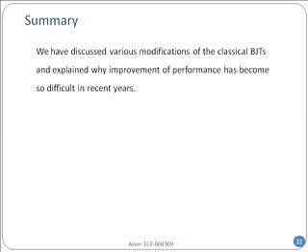So let me summarize. The basic idea is that the standard transistors of the 1950s have gone through many modifications. Most important of them is the polysilicon transistor, right? That was a great innovation. Without it, bipolar transistor scaling would have stopped in the 1980s. But it gave 15 to 20 more good years because of the polysilicon, but then the short base essentially killed it because you cannot improve it any further. You do not have any more gain.